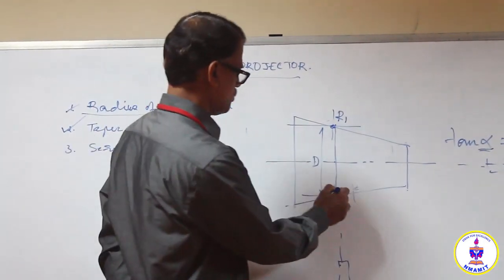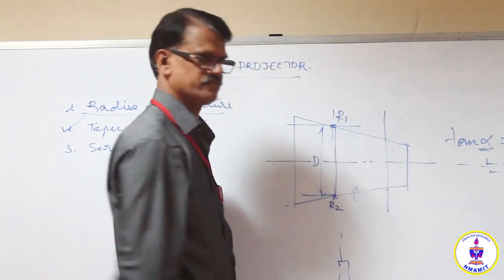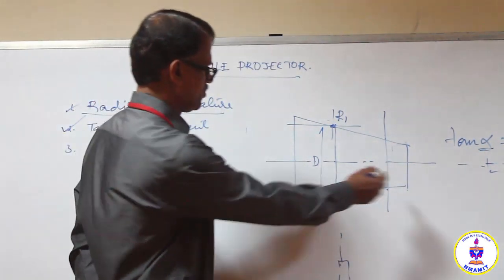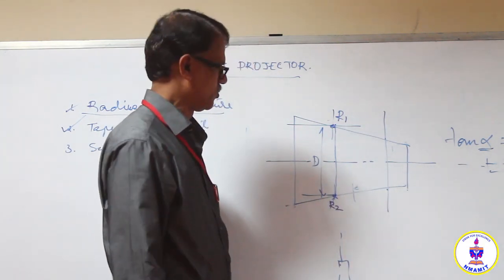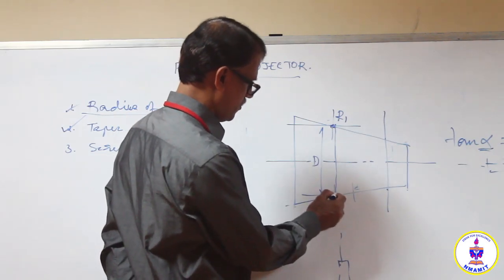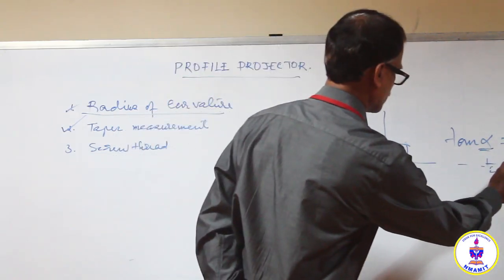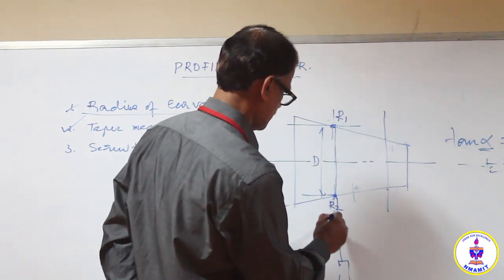Now move this one to another section and measure the diameter here also. Once you move this one here, you will not get the length between the two sections here. So without altering this position here, you record the reading on this micrometer here and take that as the first reading for the length. So this is R3.